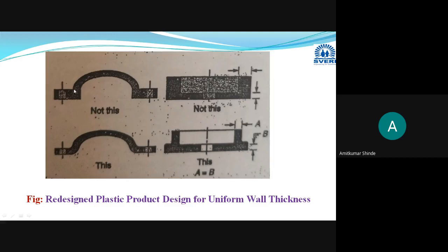Instead of this, you have to modify it in this way by providing uniform thickness throughout the part. If possible, provide uniform thickness throughout the part. In this way, for designing knobs and handles, plastic knobs, plastic handles, like door handles and knobs, these are designed.